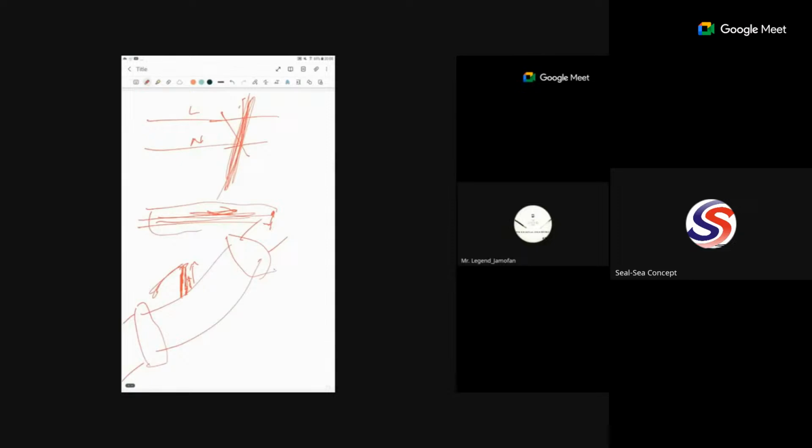Because if these beds should sway away, all the material that is here will be wasted. Sometimes the process guy will have to come and manually pack those materials. So once this bed is swaying, that is drifting off the drum on which it is being driven, it will touch this sway switch, and the sway switch will activate an output that will switch off the electric motor that is driving this bed. The electric motor will have to go off compulsorily.